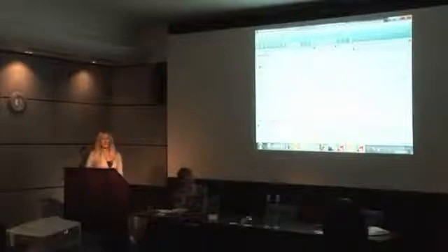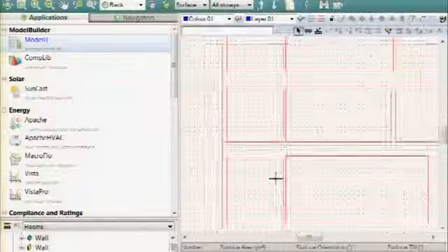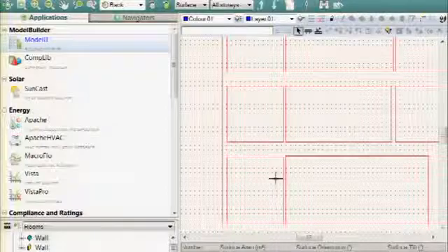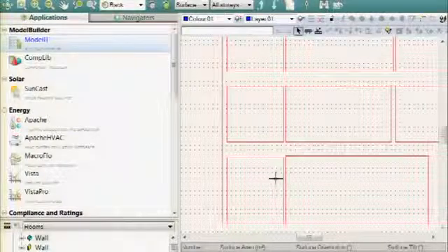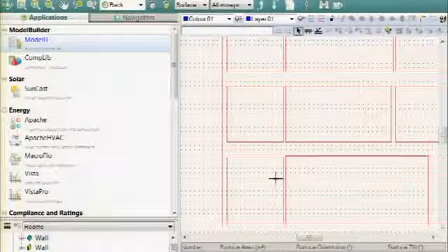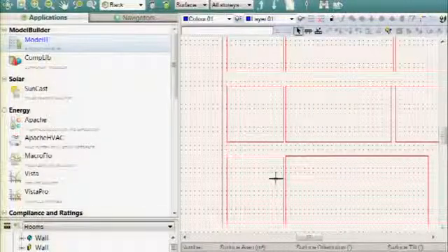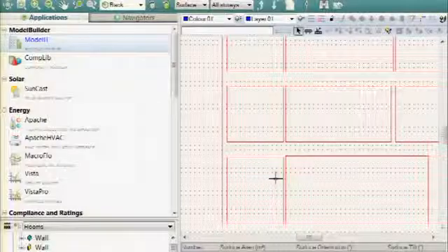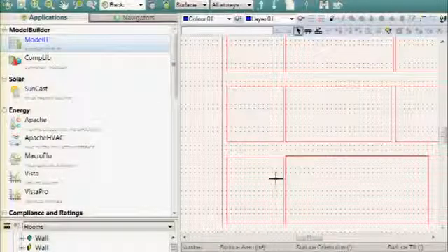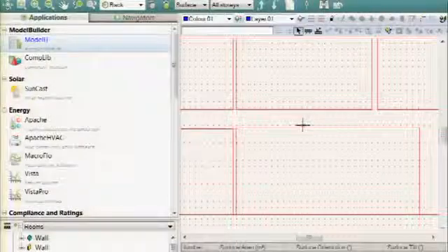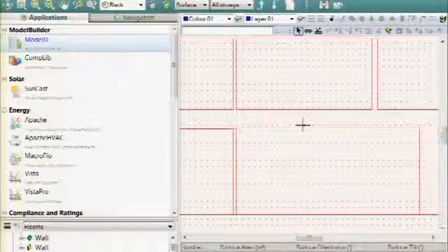So it'll depend on how bad it is. If they have overlapped a lot of frames and you end up with gaps and windows that are very off, then I would, yes, highly suggest redoing it. If it's off a little bit, you have to make that decision to see, is it going to work? But just make sure in that case they are accounting for the mullions on the curtain wall, and that they're drawing them in Revit, because then you will at least get a base of panes to start with. And in this case, we could just simply draw a construction line and copy it over. So it's not a hard fix. It gives you a base to start with.